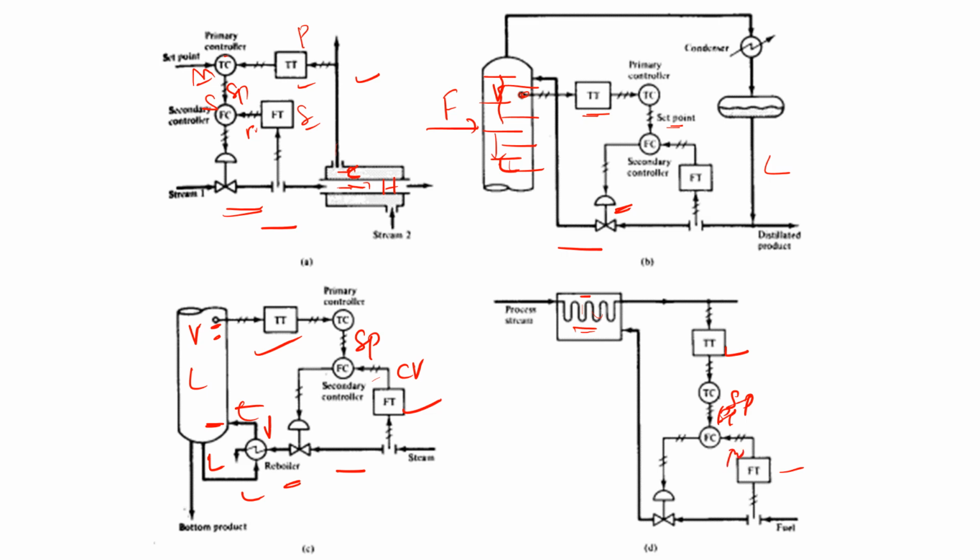This is your process variable, and then this gives error, then that is the control output. That control output is given to the control valve. So in order to achieve this temperature, the fuel flow rate is very, very important. So measure the flow rate, and you consider both temperature status and also flow status, and give the control action.